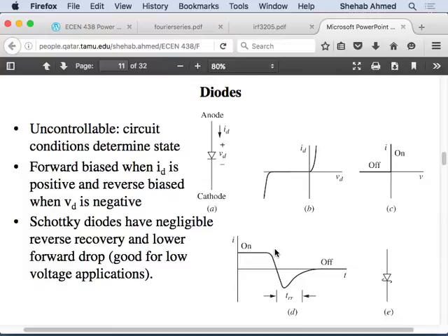So there's time required, and movement of charge means current. So this is the current that is required to build up the larger depletion layer, right? The device was on, now became off. This reverse recovery time is the amount of charge required to build the depletion layer again. That's assuming there is a negative, backward voltage on it. Assuming you apply minus VD on the diode.